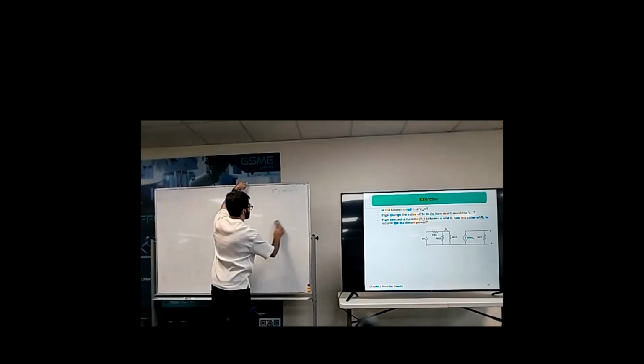I will solve it by two methods. So we have 1 volt here, 25, 50. Our systematic method is using mesh or nodal. Which one is better here? Nodal, for sure: two meshes, one node. Here ground, here 1 volt, and here we have E1, for example.